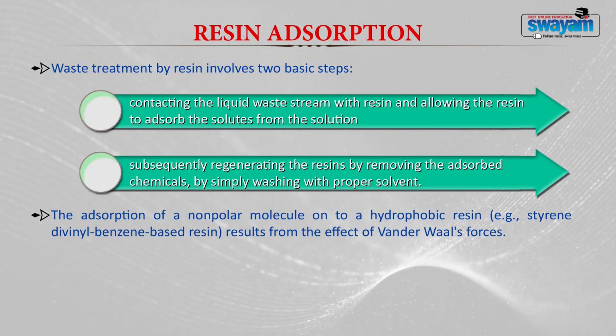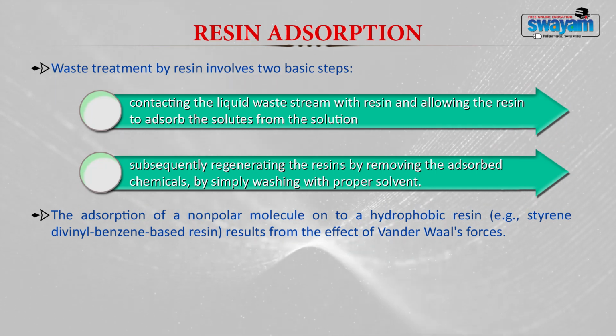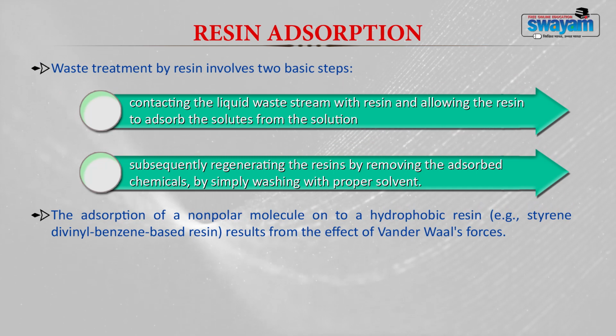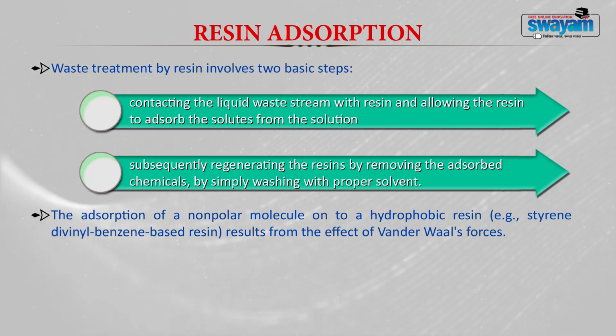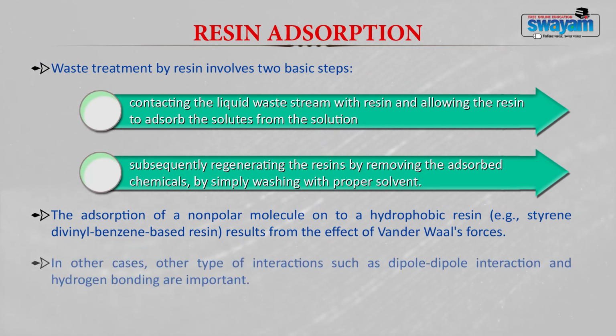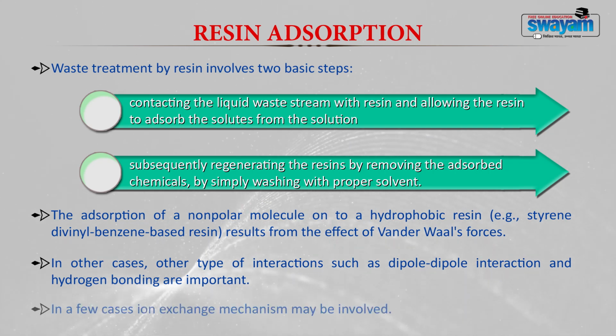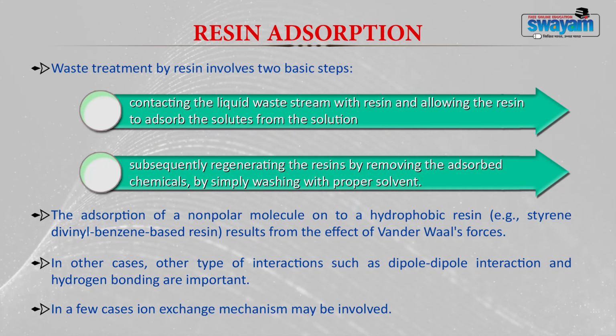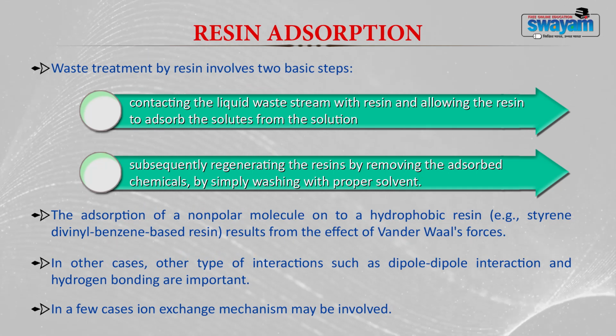The adsorption of non-polar molecules onto a hydrophobic resin generally results from the effect of van der Waals forces. In certain other cases, other types of interactions such as dipole-dipole interaction and hydrogen bonding should also be considered because they also play an important role. In certain cases, for example, an ion exchange mechanism is involved.